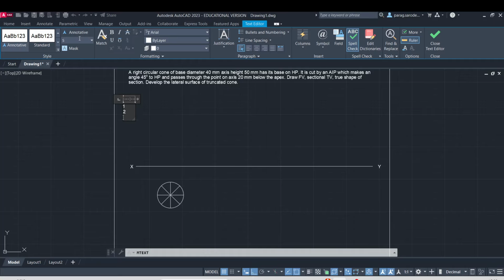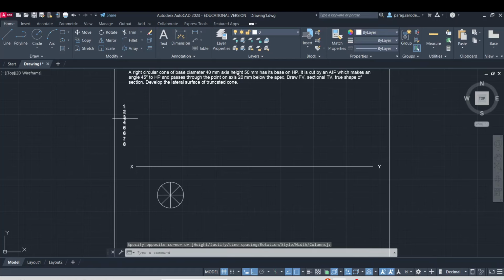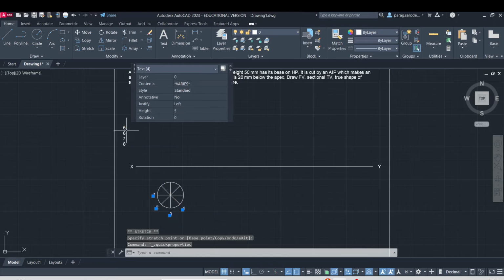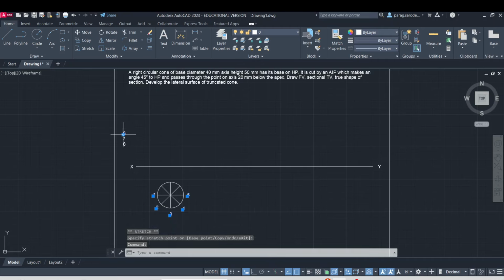Like this, we will go on adding a new line and a new name, and then we will select it together and explode it, so that we can appropriately place each point at the required location. For that we switch off the ortho mode. Let us take this 2, transfer this 3, transfer 4, transfer 5, transfer 6. We need to choose carefully, otherwise the OSNAP will fetch it towards the nearest point. So in this case you might have to switch off the OSNAP if required.